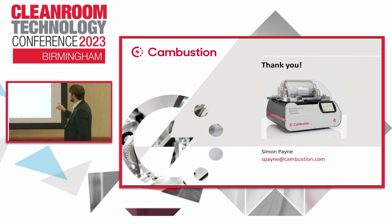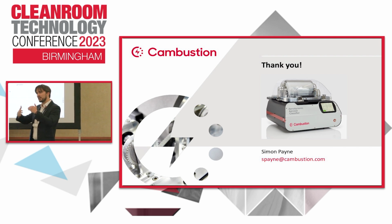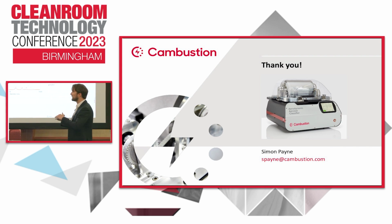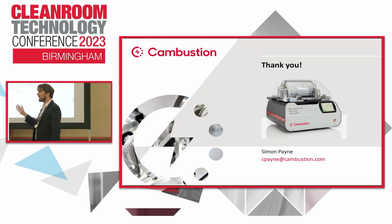That's true, yes. If you're bringing in larger particles that are above the most penetrating particle size, it is going to artificially lower the penetration result and indeed make a filter perhaps look slightly better performing than it is. I have tried to quantify that for the particular experiment we did on the right-hand side there. We have selected a worst-case scenario for this problem and illustrated it here.